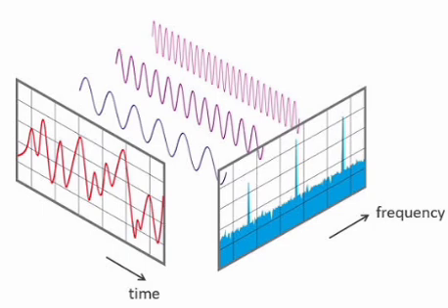Discrete time Fourier transform. The definition of DTFT: consider a discrete time signal x of n. Its discrete time Fourier transform, DTFT, is defined as DTFT of x of n equal to X of omega, equal to the sum from n equal to minus infinity to infinity of x of n e power minus j omega n, where omega is the discrete time frequency in radians. The transform X of omega is a frequency domain description of x of n.